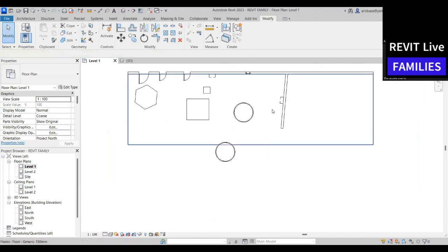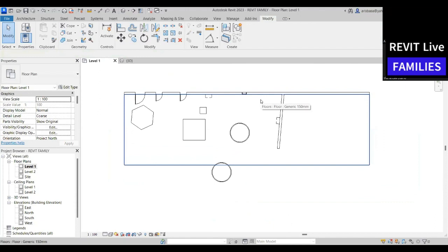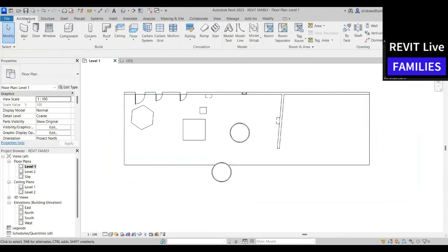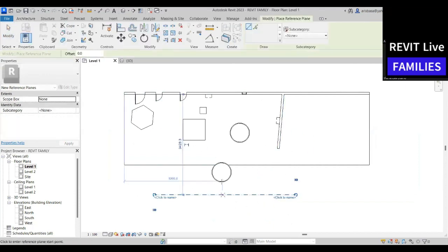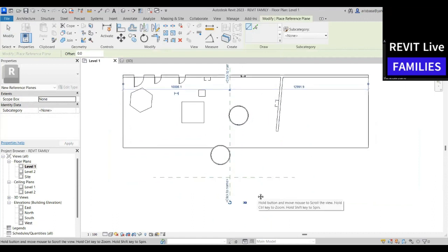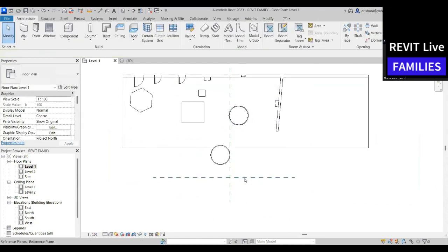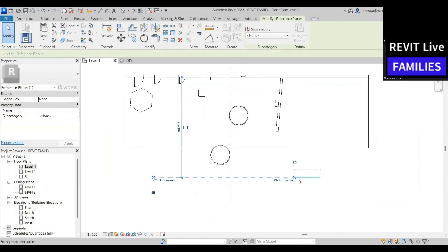So actually, when you're doing this, and let's say you don't have any wall, it would be best to create your own reference plane. Let's say here, you can have a reference plane here. That's why when you see those families earlier, they have the reference plane, and then you can name this. For example, this will be for profile. Okay? And you can name this also profile 2.